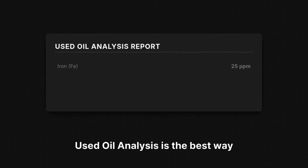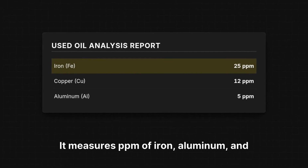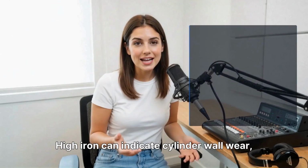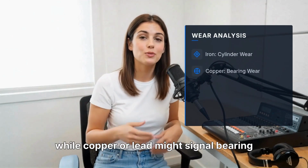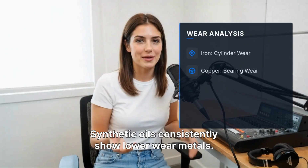Used oil analysis is the best way to see how your engine is wearing. It measures ppm of iron, aluminum, and copper. High iron can indicate cylinder wall wear, while copper or lead might signal bearing issues. Synthetic oils consistently show lower wear metals.